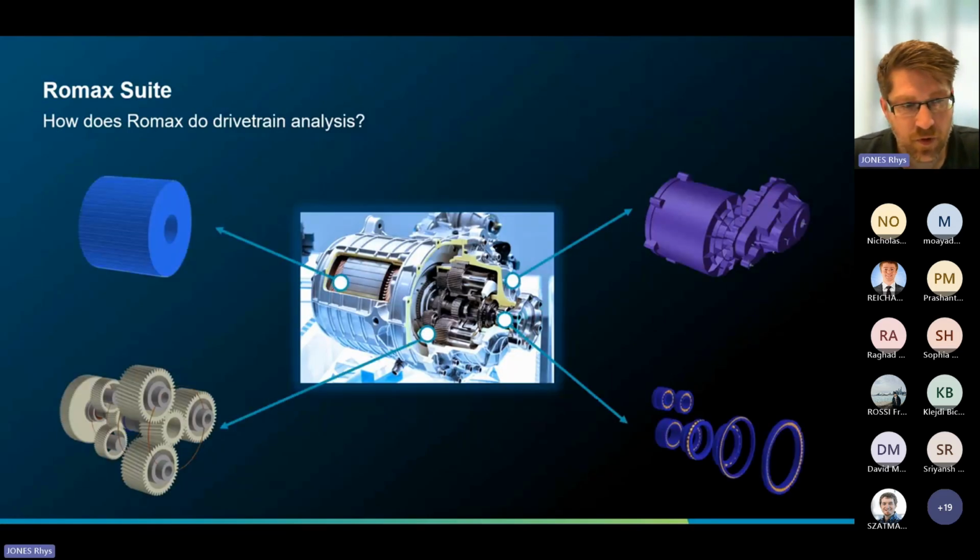Well, we can take a gearbox and we can split it up into its component parts. And at different components, we can give different levels of detail. So for example, on this, well, to be quite frank, luckily for us, this is quite similar to the transmission that I'm going to demonstrate shortly. We have within here a planetary system arrangement. So these grey shafts here, the underlying principle of those that you'll know from your engineering degrees, it will be a Timoshenko beam. So it's quite a simple, lightweight solution for working out the deflections of the shafts.